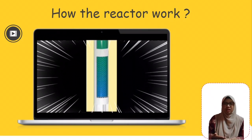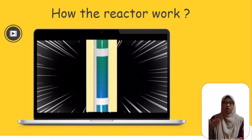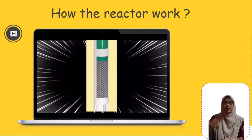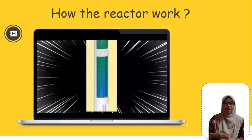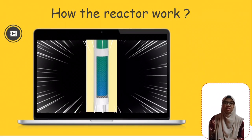The animation on the left shows a basic operation of a packed bed reactor. The reactants, which are the green color, enter the reactor at the top and then flow through it. Upon entering, the reactants flow through the packed bed of catalyst. By contacting the catalyst pellets, the reactants react to form product, which is the blue color, which then exits the reactor at the bottom.